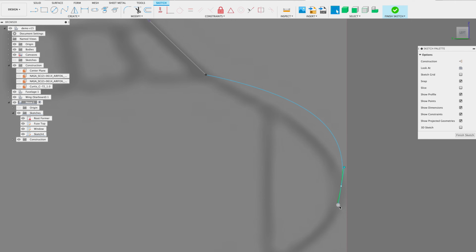Now, one thing to note before I show you how to do this: if your tool is more than 45 degrees and you press the horizontal/vertical, you will notice what it will do. Let's activate that. You'll notice it will actually turn it horizontal, parallel to the floor, which is what we don't want. What we actually want is for this to be higher than 45 degrees, and then when we activate that and press the horizontal, we'll actually get it perpendicular to the floor. All right, so let's escape out of that and let's start our adjustments.